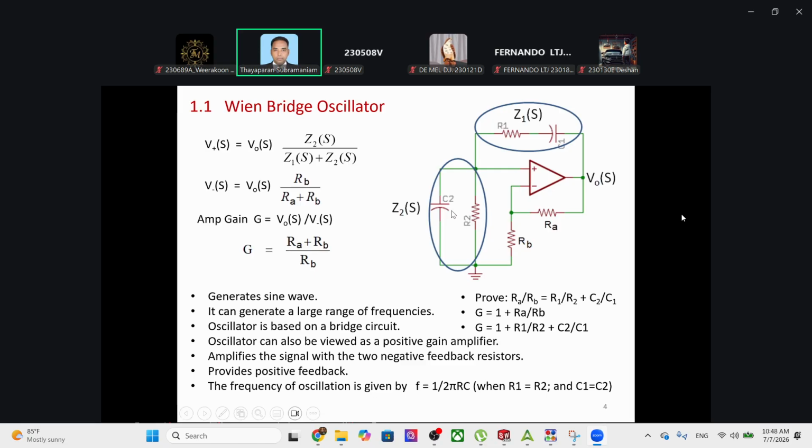Right. Therefore, the current through C1, C2 and the current through R1, R2 should be considered, but again, we have one condition here. The current through C1 is equal to the current through R1. The problem comes when the current through C2 and the current through R2 can be different.